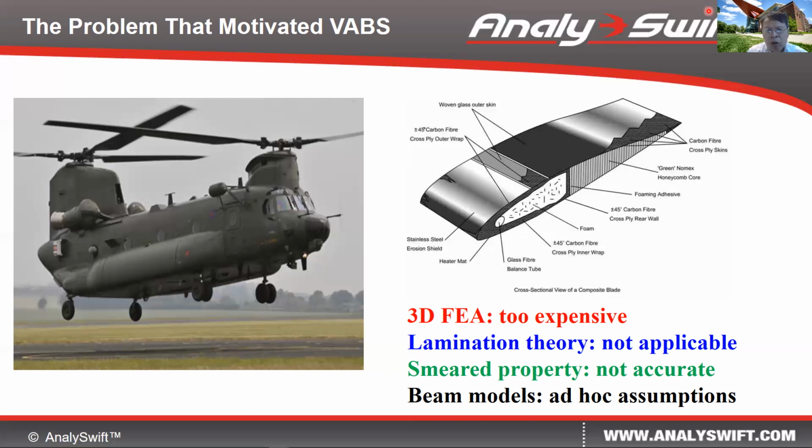In principle, we can use 3D FEA to provide a high fidelity modeling of this structure. But because the layer is so thin, and each layer could be different, to get accurate stress prediction we need to have at least one solid element per layer. Then for a blade, we are talking about billions of degrees of freedom, which becomes too expensive to be practical, if at all possible.